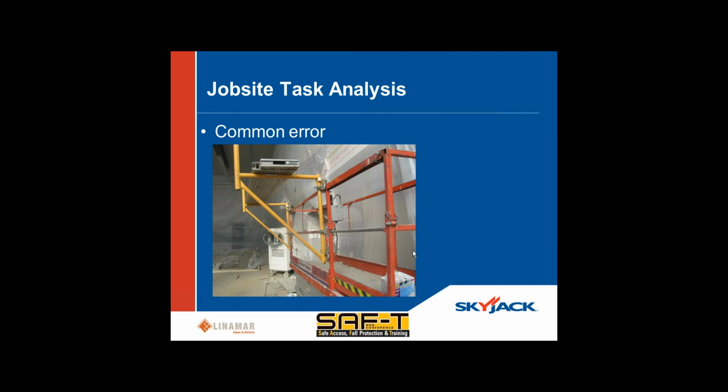And I think a lot of people believe that the factor of safety on these machines is much greater than it really is. Certainly there is a factor of safety related to stability, and we all have to meet certain standards when we test with respect to stability, but doing things like this and cantilevering loads can make you become unstable very quickly.